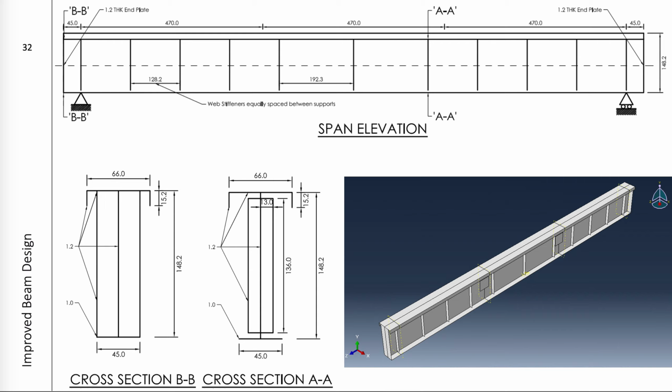The improved design firstly replaces the central 2 stiffeners with a single one. Attempting to discard these stiffeners without replacement caused the beam to fail before 12 kN, meaning the new central stiffener was required. This is likely related to the local contribution made by the stiffeners to IZZ, which influences resistance to the critical failure mode, LTB. The end plate was also reduced to cover only the width of the bottom flange.